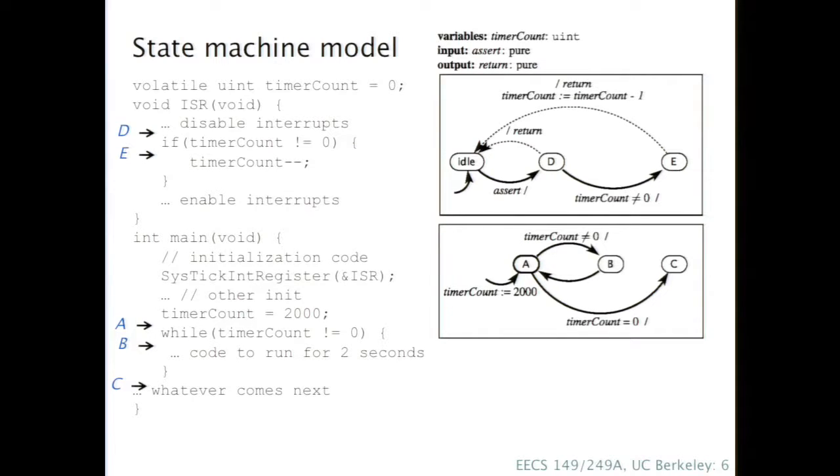Now, how that plays out in terms of timing is actually not expressed in this C program at all. And how it plays out in terms of timing is going to depend on the hardware that you connect up to this thing. What does the timer do? How does it handle toggling of the interrupt request line? What if the interrupt request line transitions during the time that I'm executing this interrupt service routine? Will it respond to the interrupt after it's done when it enables interrupts or not? That's up to the hardware, and it's actually not expressed in this C program.